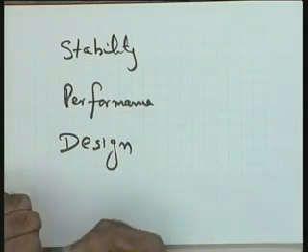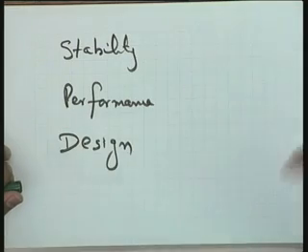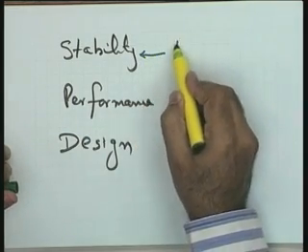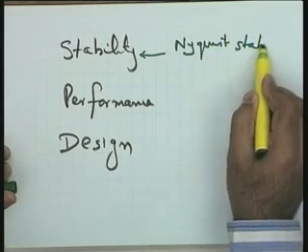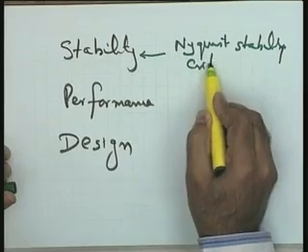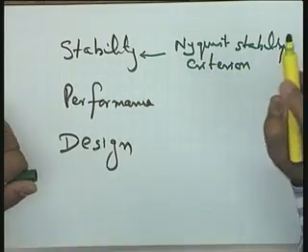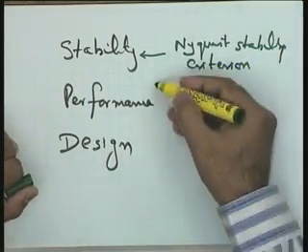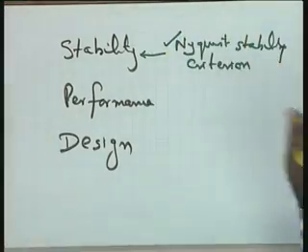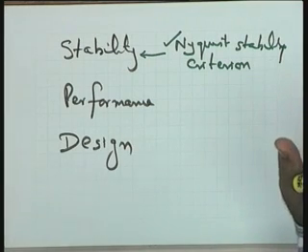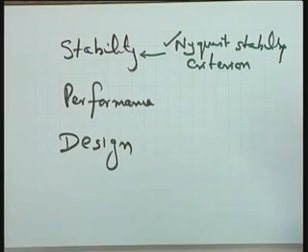In the root locus method, stability could be determined by the Routh-Hurwitz criterion or directly by the root locus. Here, a stability criterion called the Nyquist stability criterion is available to us, developed by Nyquist, a very important criterion. Rather, the frequency domain formalism is centered around this Nyquist stability criterion. This is the key feature of the total analysis and design method. Very important point, the backbone of the total frequency domain design methods.